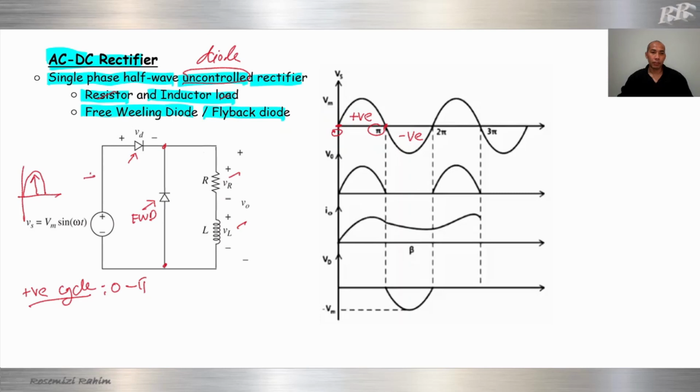So current will be plus minus like this. Same, plus minus. So current will flow in this direction from the positive terminal. So we can see the diode arrow like this, and the flow of current like this. Due to the same arrow direction, this diode will become forward biased, or short circuit. So during the positive cycle, the diode is short circuit.